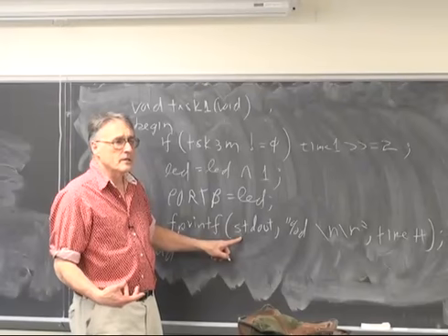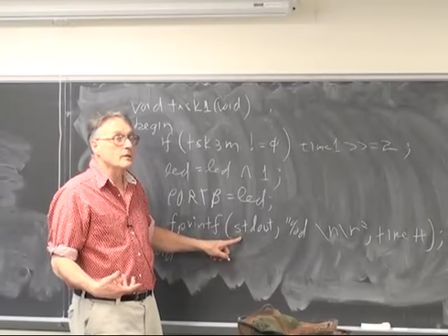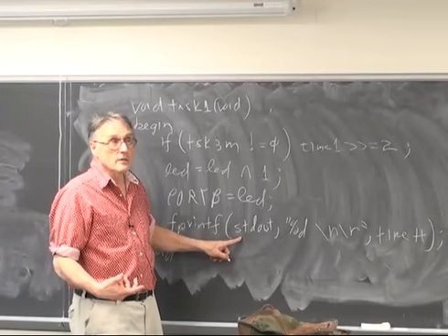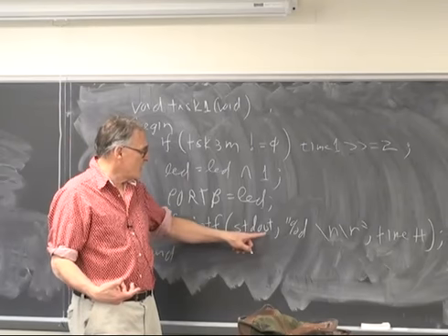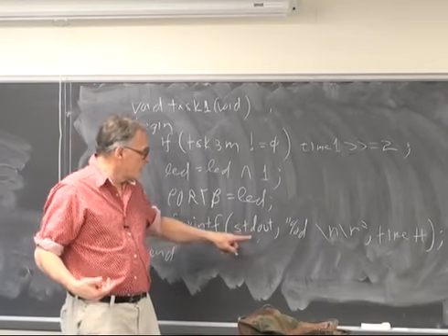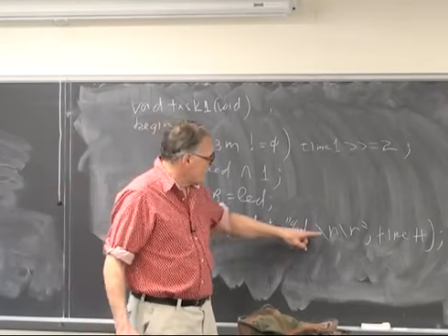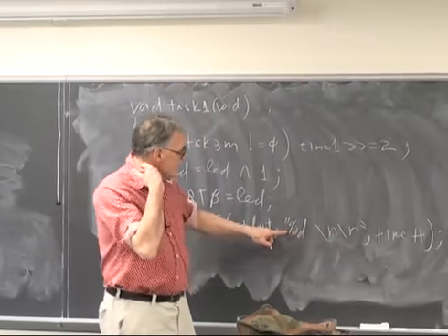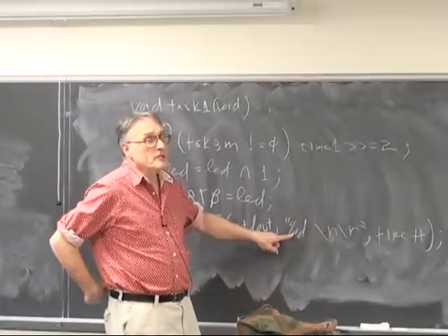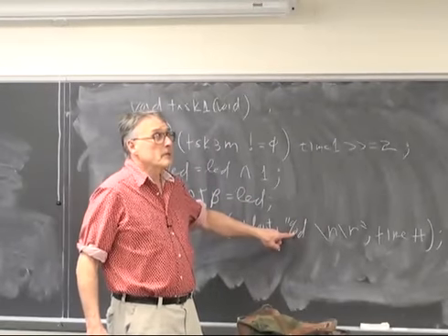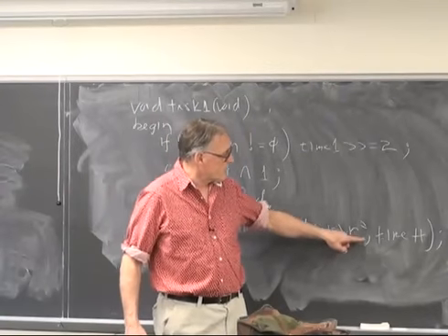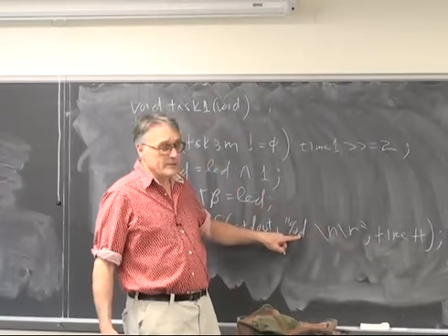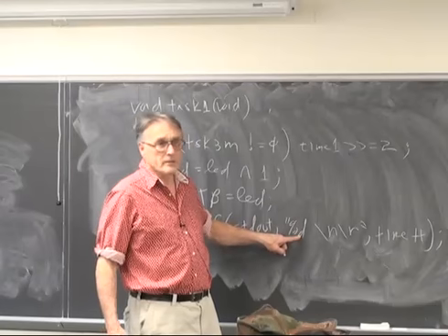Standard out is what was defined in the UART initialization file definition as the print unit. Then this %d \n\r. %d says take the first parameter in the list after the current parameter, convert it to a decimal integer, and format it.